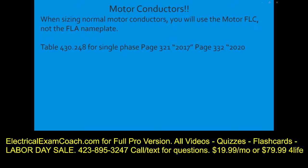Okay? One thing I want to note is that these are nominal voltages. So although it says 115 at the top, it would also include 120. Although all the way at the end across the top of the black bold headings, you could still count 240 in that. These are nominal voltages. Another tip I want to give you is that even if the motor is a single phase motor, but your question states 208 volts, you use whatever column your question states. Don't try to use reasoning and say, well, 208 is only three phase. Whatever your question states, just do it that way.